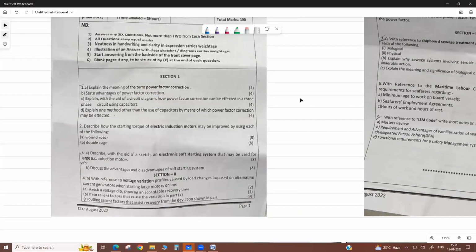Your load current is reduced, so the voltage drop in the circuit is reduced and losses are reduced. Otherwise the load current is increased and I square R losses will be high. Efficiency is improved, and your electricity bill is reduced. The adverse effects are avoided. And the load on the transformer or alternator is reduced at high power factor. That's why we improve the power factor. Correct.